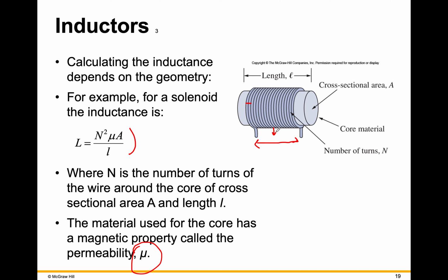And so that diminishes the value of the inductance because you're not keeping all of your field in this solenoid. So in reality, this equation is an approximation that is only as good as how tightly wound your coil is. And no coil is perfect, so this is never a perfect equation.